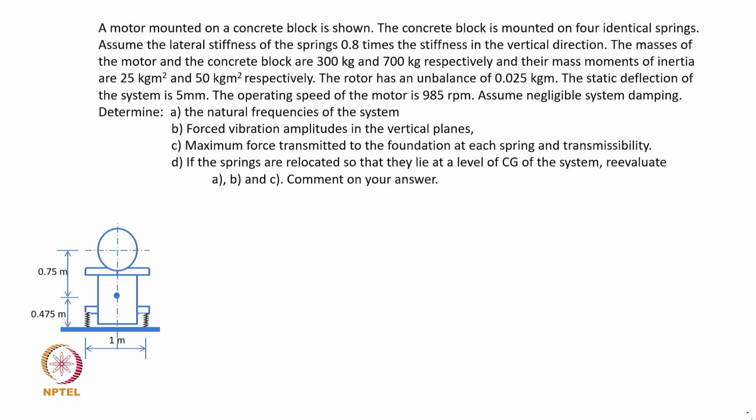Basically, it is asking us to figure out what are the natural frequencies of a system which is like a motor mounted on a concrete block that you see here, and this motor is generating excitation. Obviously, maybe the CG is located somewhere here, and it is quite similar to the box vibration case that we discussed a few slides back. So, it is going to have x degree of freedom like this, the theta, and of course y.